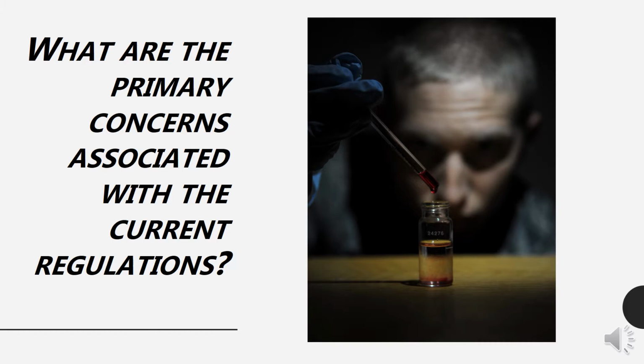This is especially true for source waters with high bromide concentrations, as there are greater health risks associated with brominated disinfection byproduct species. There's no evidence that the 11 regulated disinfection byproducts are surrogates for the unregulated disinfection byproducts.